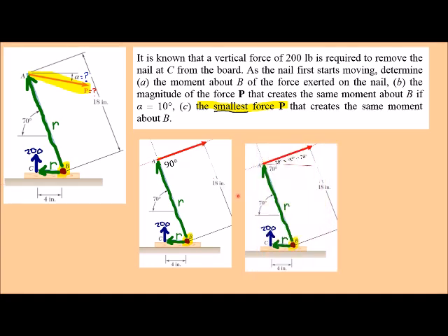So if that's 90 degrees, take that 70. 70 over here is 70 up here. So we're looking at something coming up at 20 degrees. And to figure out what that force is, rather than breaking everything into x and y components, it's just going to be the position vector times the force. They're already 90 degrees with one another, so you don't have to go through that cross product at this point.